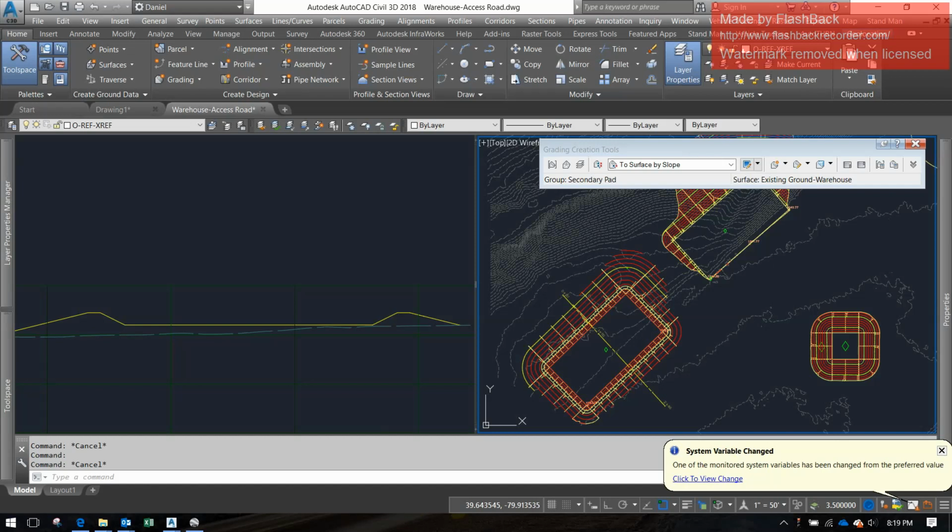So if you have like a big frac pad that has 6 silos of natural gas on them, those silos are going to be much, much higher than your mountable berms. So they have really large, enormous volumes. You need to make sure that the mountable berm is high enough to contain all the liquids and all the volumes of gaseous material that would occur if that tank was breached and the mountable berm was the only thing keeping our fishes alive, you know.